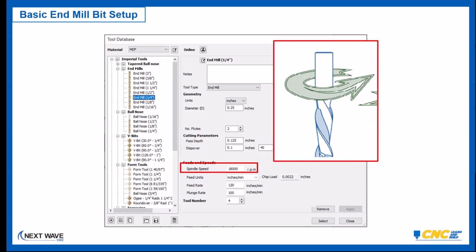Industrial machines, surprisingly, or mid-size cabinet shop machines, will often run theirs as low as 12 or 14,000, but they're also dealing with a 4, 5, 6, 7-horse spindle. So that spindle has a lot of torque to drive that bit through the wood. On these smaller benchtop tools, you have to run them slightly higher than what might be recommended by the bit manufacturer in order to maintain the inertia of the bit going around. We're going to take a closer look at this. Also, I have a table with some specific numbers in it.